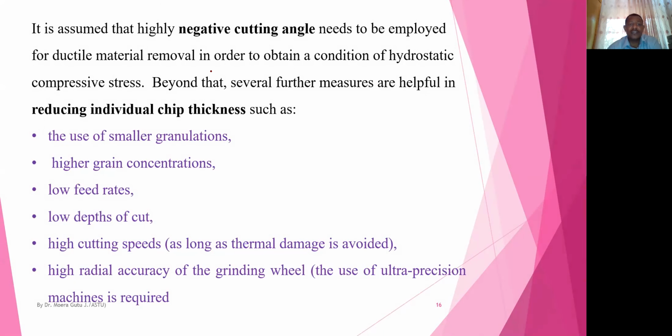It is assumed that highly negative cutting angles need to be employed for ductile material removal in order to obtain a condition of hydrostatic compressive stresses. So a negative cutting angle for a cutting tool engaged with a workpiece, when machining ductile material, imposes hydrostatic compressive stresses.